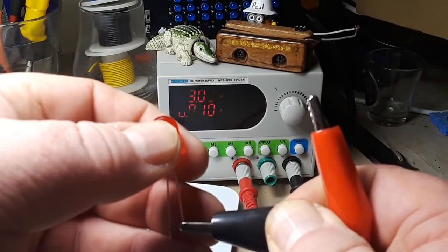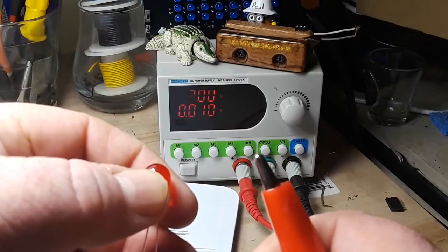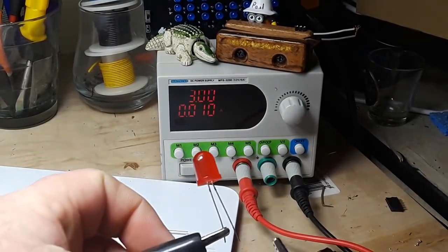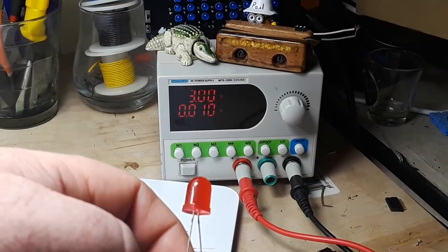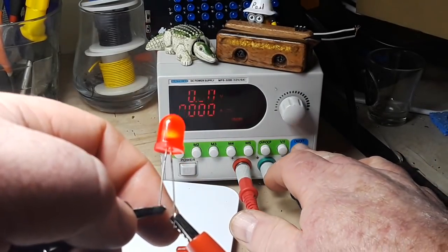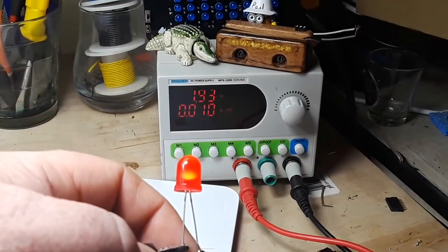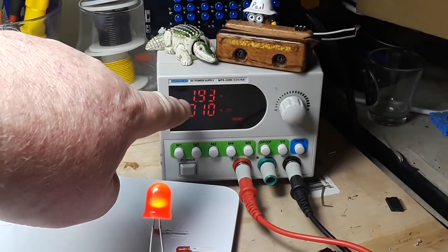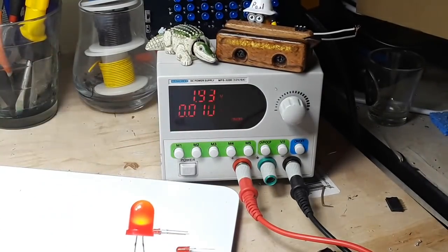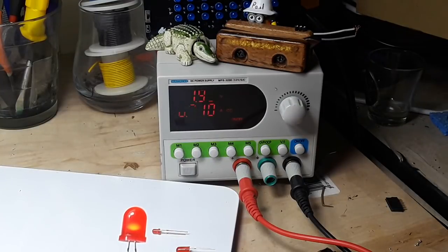Short leg is our cathode, our negative. That's the black coming off my power supply. Long leg positive. Make sure we're separated. We want to avoid shorting them out. Turn it on. So the LED is lit, which you can obviously see. And you can see from 3 volts, we are at 1.93. So you can calculate their voltage drop from there. 1.92, close enough. So that's our 10 millimeter LED.